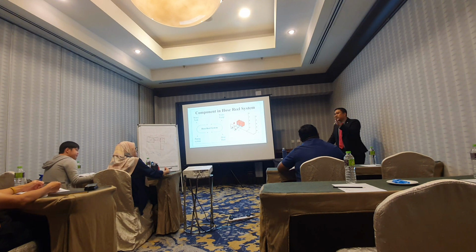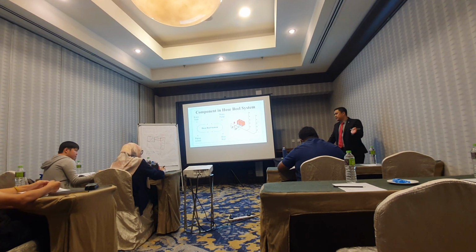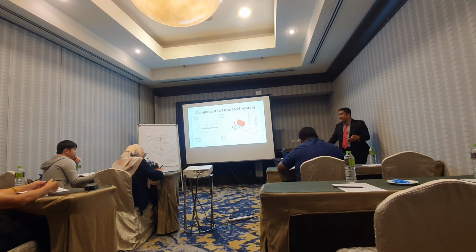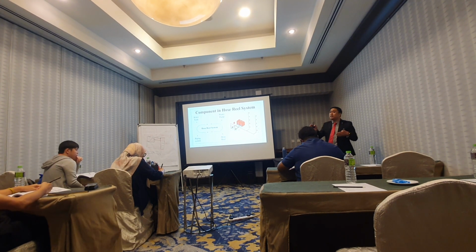You just do the C1, C2, C3. Shock test has to be done, but it's not as stringent as what you would want for a sprinkler system or a wet riser system. Hose reel is just a pump that complies with MS 2616 and has fire rated approval. That's all. It means UL can be used, but when you install and test, you have to follow the MS2616 regulation.